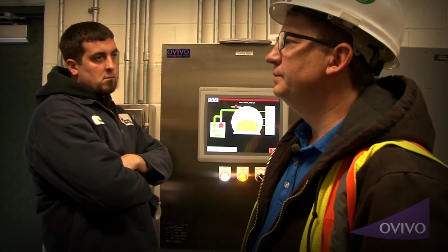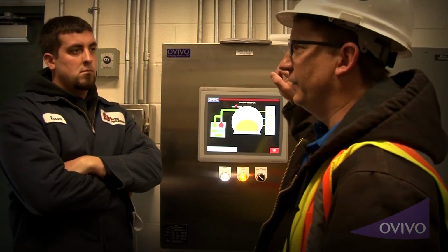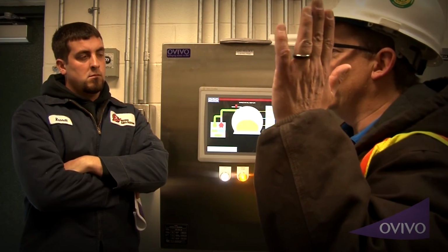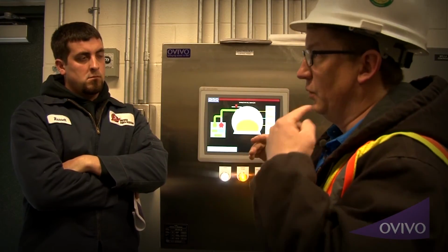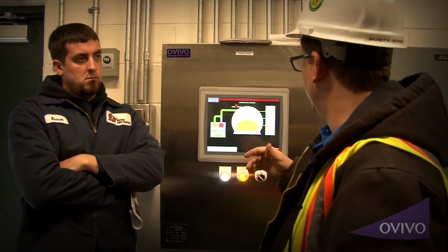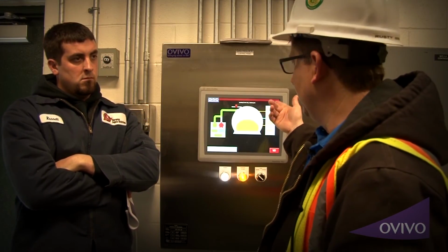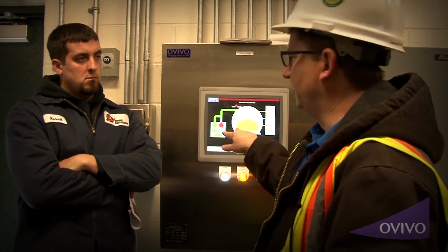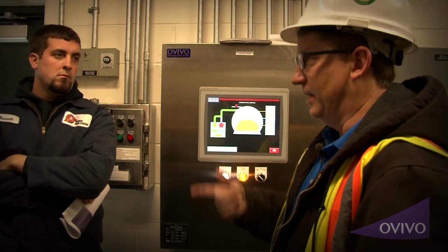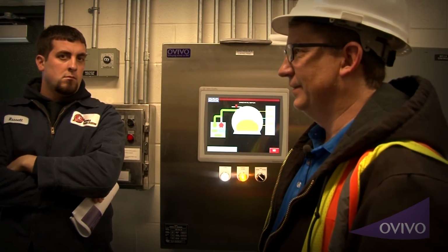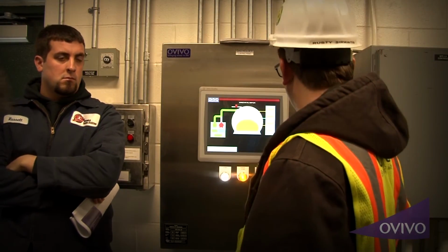What's that? Why did you just get a low air pressure? When I turned it off, there was still air exhausting out of there, but no fans were turning on because I turned it off. So the air pressure came down below 1 inch of water column. That sent the alarm. And then when I turned it back on, both blowers came back on to compensate for it. That's because I killed the power to it. Okay, that makes sense.